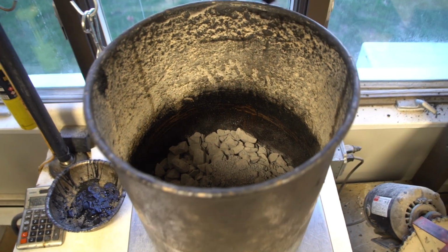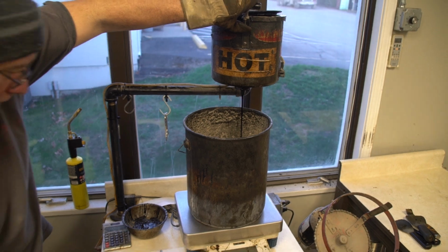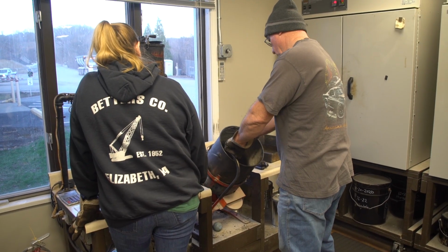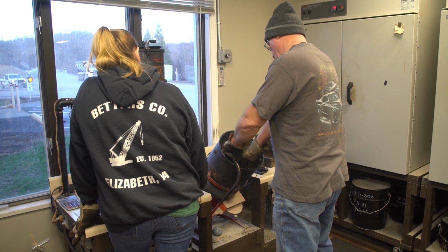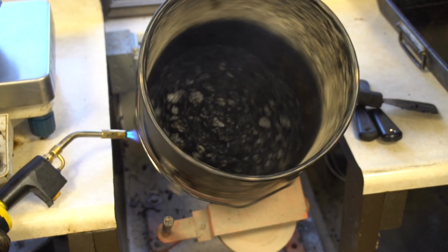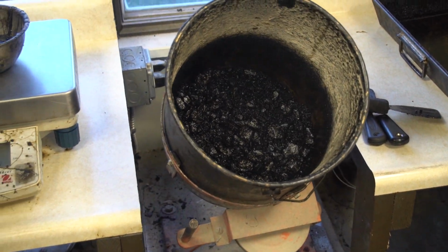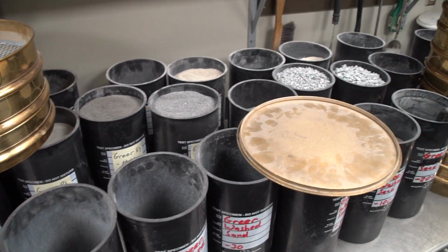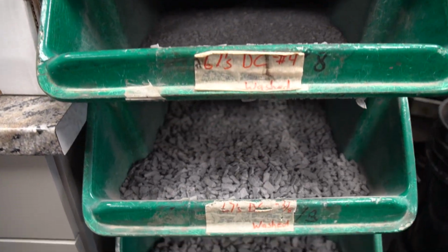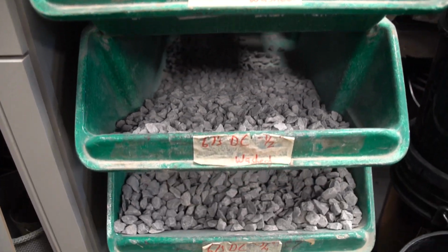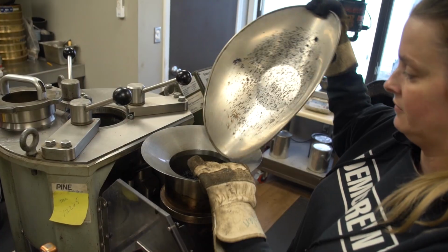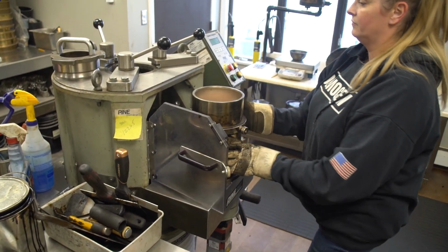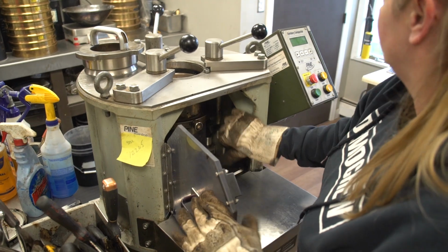Before any asphalt can be produced by the plant, we must first create state-approved mix designs. Here in the QC lab, they create sample mixes by replicating the same processes as the plant, but on a smaller scale. They have all the same aggregates, wrap, and AC that the plant does when making these samples. With the equipment you see here, the QC lab produces plugs which replicate compacted asphalt.